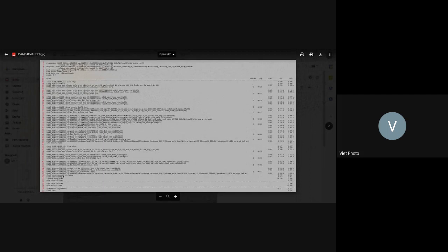However, now you have a clock reconvergence pessimism. This one is a value that, okay, just ignore it. I think if I explained that it would be too long. Just ignore this one. The clock uncertainty here is 53 picosecond. What is clock uncertainty? Clock uncertainty is, this one is still STA, right? It will model the clock skew.